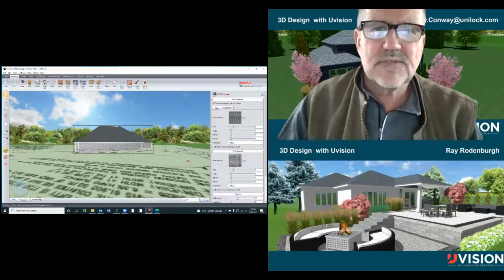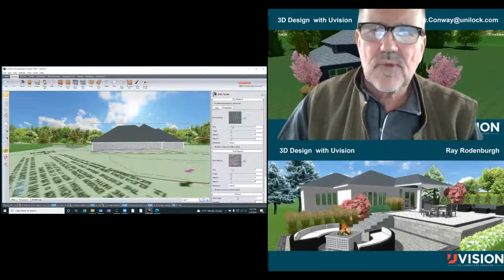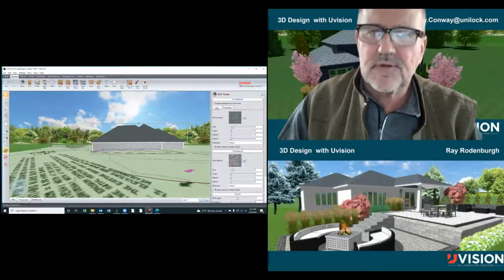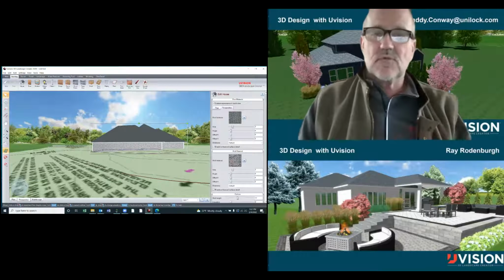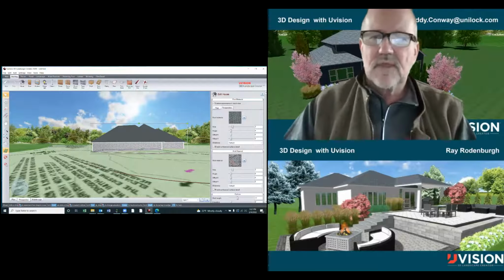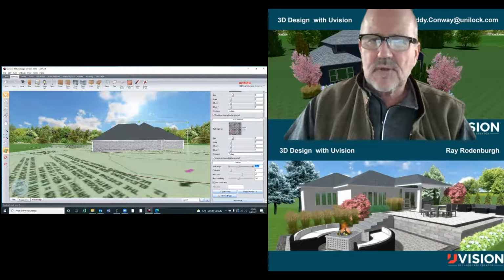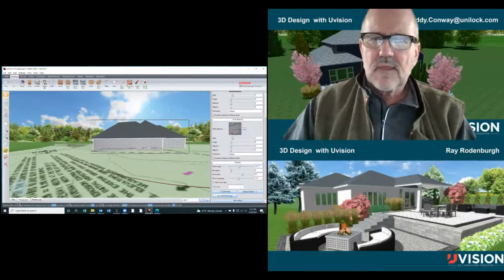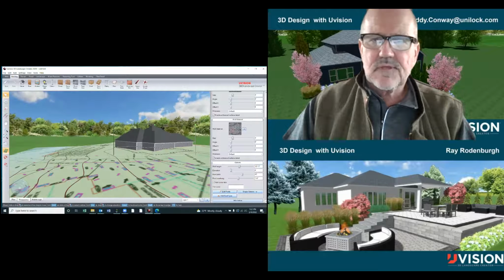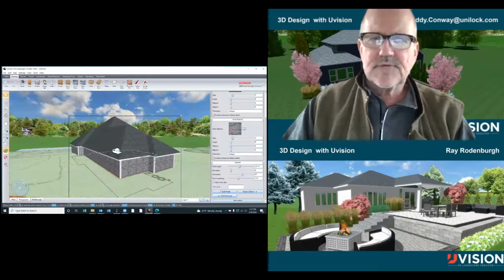You raise it accordingly. You might take a reading off the blueprints, how high the gutter line is above this point here. And by raising the house up, you can designate that one point. And if I do that, it will affect all the other points in the house. So if I go to here and just jockey up, you can see how it affects the rest of the house.